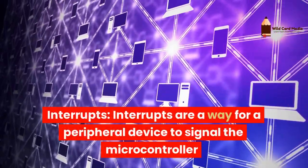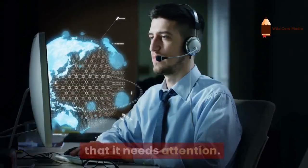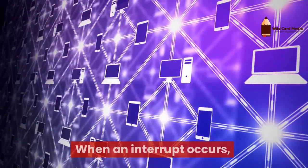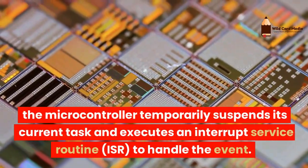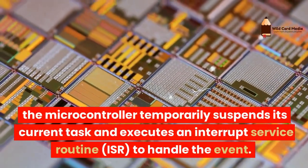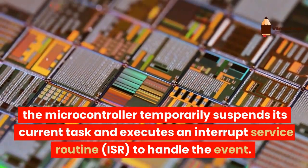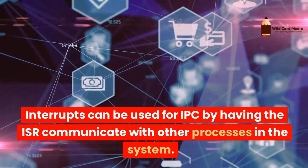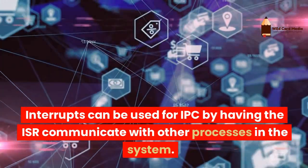Interrupts. Interrupts are a way for a peripheral device to signal the microcontroller that it needs attention. When an interrupt occurs, the microcontroller temporarily suspends its current task and executes an interrupt service routine, ISR, to handle the event. Interrupts can be used for IPC by having the ISR communicate with other processes in the system.